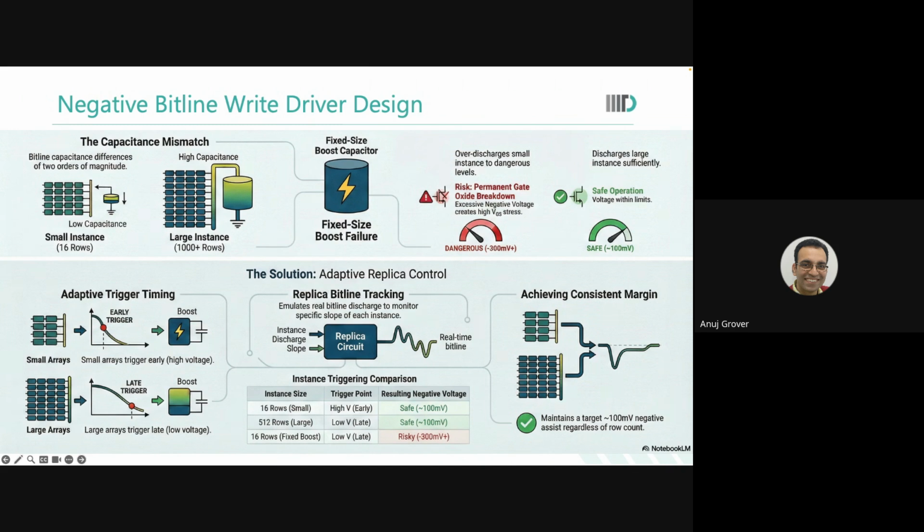Let us say this is the capacitor for the write driver. This is the capacitor for your bit line. And over here, you had a voltage source. This voltage source, when the switch was closed, would discharge the CBL. There is another replica that I have, which is a similar voltage source, and it will track. That's a different thing. It will discharge the CBL. If I allow it to discharge for a longer time, the CBL will almost reach a voltage level of 0.